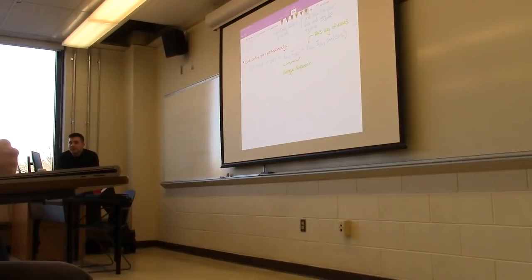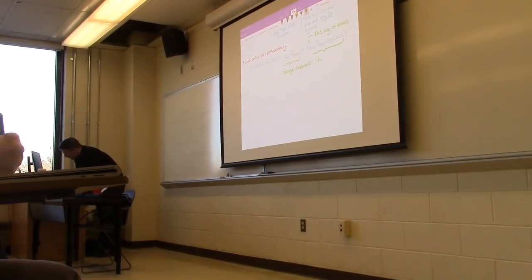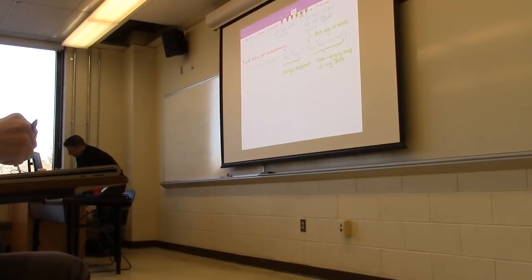The average of a cosine is 0, so that fades away. We'll just be left with the non-time varying component. So we have the average component, and then we have the time varying component with an average of 0. So the first term is going to be the average power. Yes. Okay, now the second case.